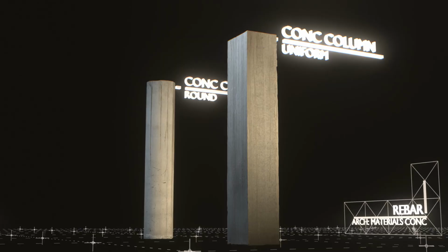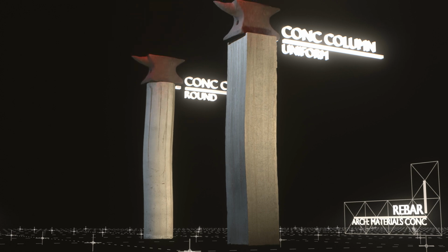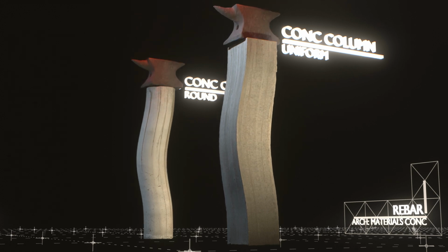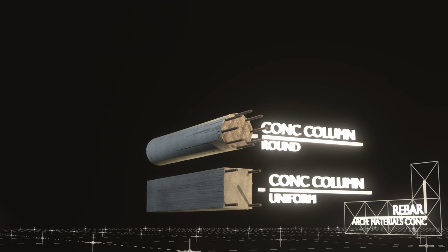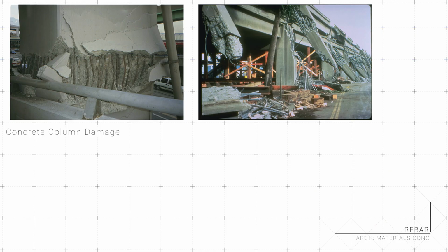Concrete columns too undergo tension where heavy weights above can cause buckling at the side, or sideways lateral movements like earthquakes make a column behave like a beam, by applying lateral force at the sides. As such, columns also are imbued with rebar skeletons. Buckling especially can happen on all sides, so columns are reinforced symmetrically across, unlike beams. Longitudinal bars within beams and columns have in the past busted out at the sides under heavy buckling or through wear and tear over time.